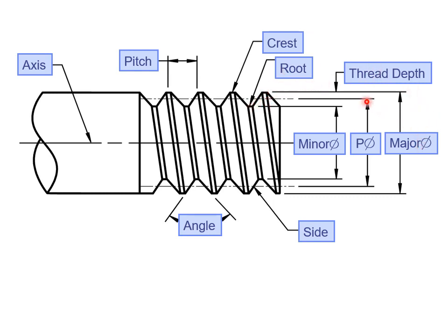Okay, here we have the major diameter, which is the distance from crest to crest. That's the major diameter. Minor diameter is from root to root. And the pitch diameter, it's not exactly in the middle or the average. It's where this line equals this line. So the distance from the tooth itself, with the depth of the tooth here, and this length here equal each other. And you go to the opposite, and that'll give us our pitch diameter. The one that is important is the major diameter. Okay, and then we have the angle and the sidewall.